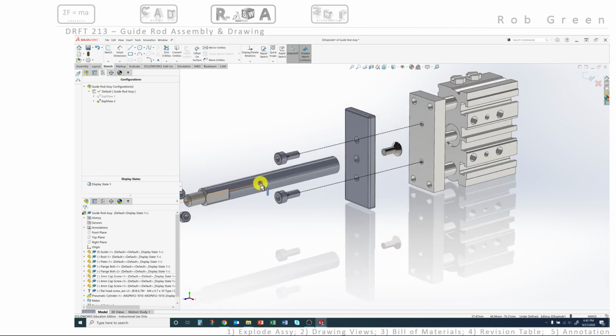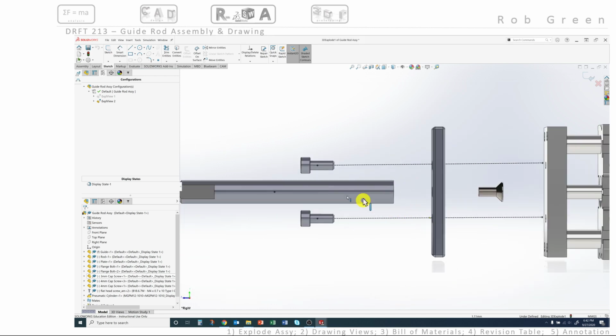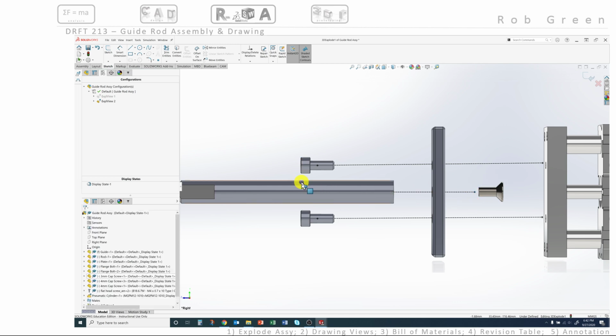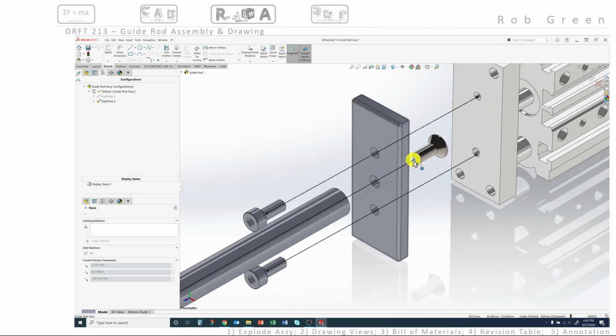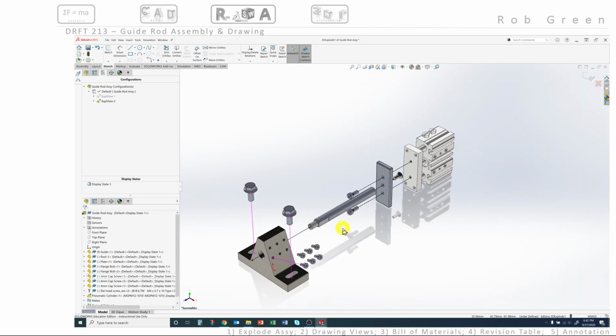All right, so then I need to drag this line out to that screw. I'm still going to trust my 2D view, and I will drag this over all the way through, I guess just short of the screw. And let's see what I got in 3D. Kind of came out to the edge, put it back in there so that it looks good in 3D, and now I have those assembly lines that are needed. So I'm going to rebuild this and save this file. Right, I have all the lines that I need.